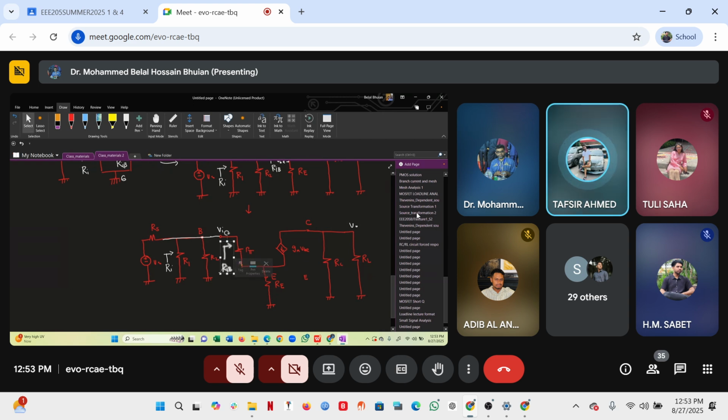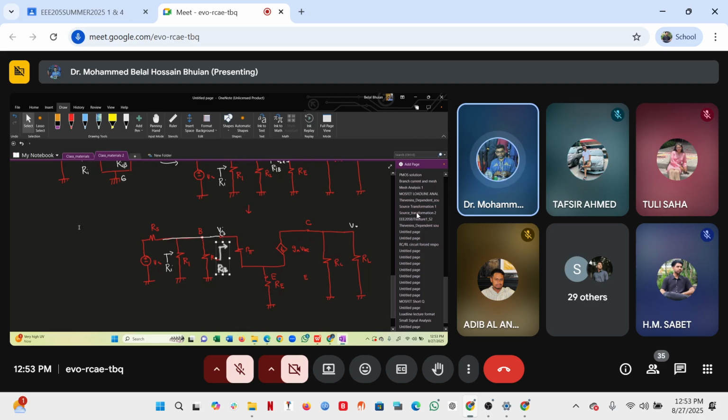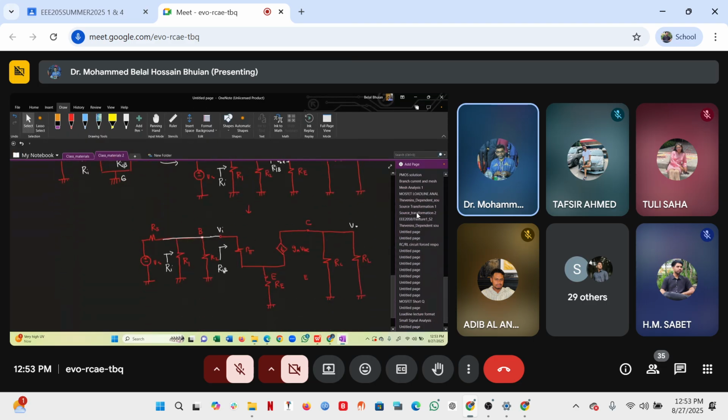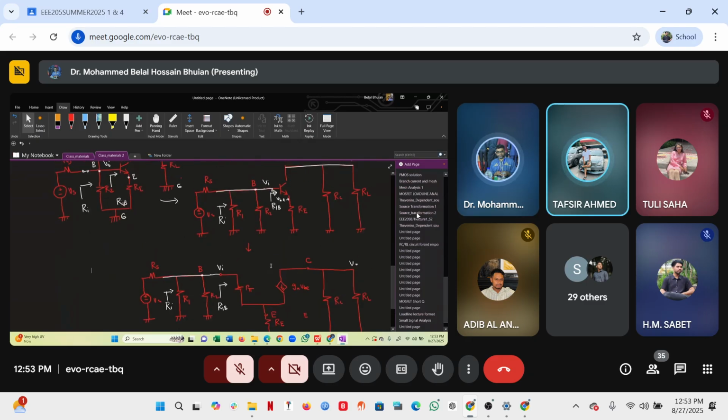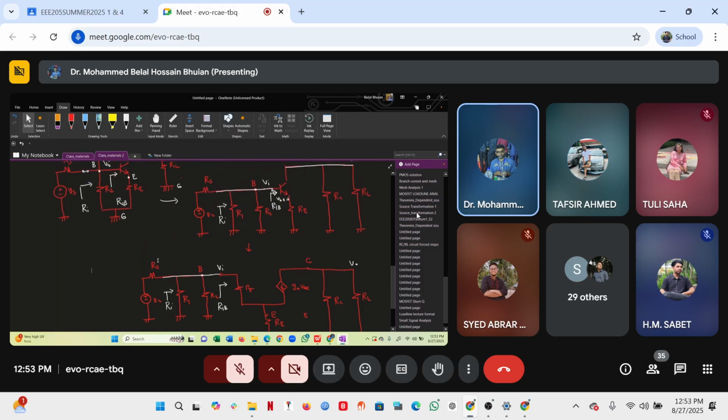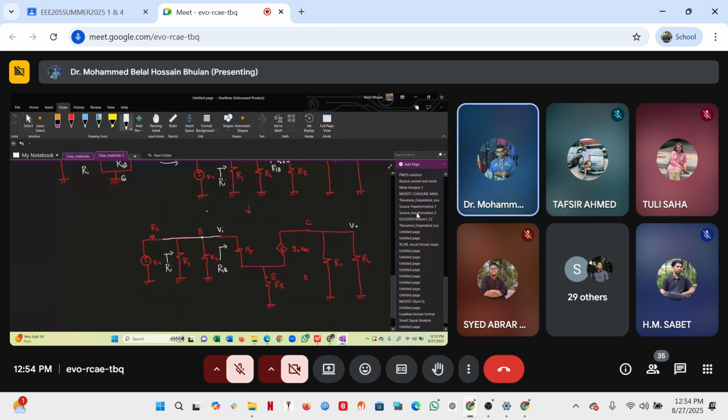This is the AC signal model, meaning the small signal model. From now on, what I'm doing is a small signal model, only for small signal. You see this circuit doesn't have any DC signal source, and this is a simplified diagram. Don't confuse VS as a DC signal. Drawn this way, but it's an AC signal source.